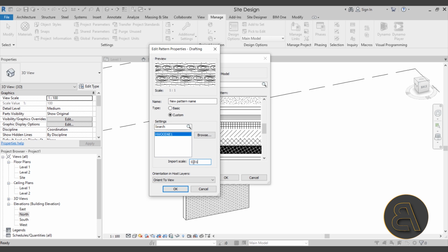So you have to play around with scale a little bit, try to go 10 to 100 to 200, I don't know, 1000, and if that doesn't work, then go with 0.1, 0.01, 0.001, and so on until that preview window shows your scale, or shows your hatch. Now you can find unit, maybe go with 0.02 or 0.05, depending on what you want to achieve with this, maybe 8, I don't know.